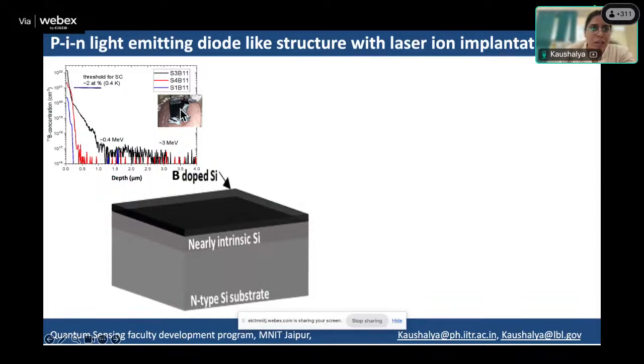If you look at n-type silicon after the boron implantation, the boron concentration in your silicon material is as shown here. In the top few hundred nanometers you have about 2% of boron in silicon, and then the profile, as you can see, is like this. Up to, say, a few microns, you have a certain concentration, and so forth.